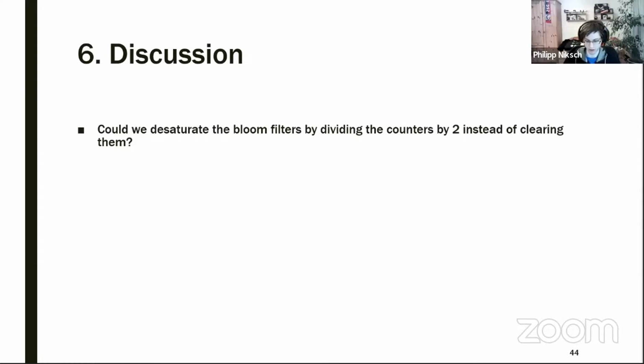So back to your question for a second. The whole implementation takes about 0.14 millimeters squared, and the dual counting Bloom filters take 0.11, which means that's like 60–70% of the whole area cost required by the Bloom filters. So cutting that area cost in half would basically translate to an area decrease of 1/3 in the entire system.